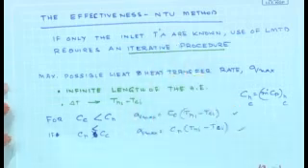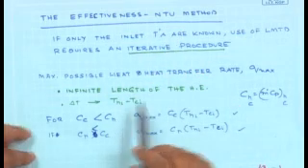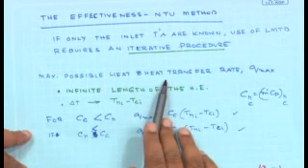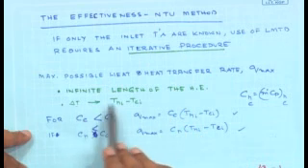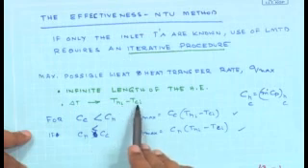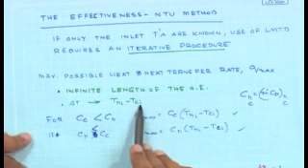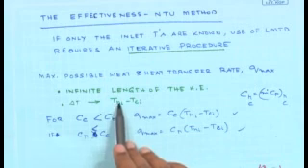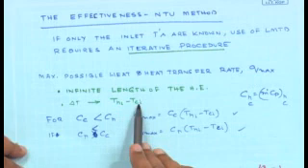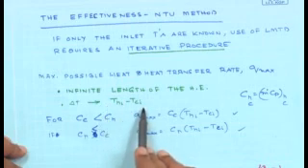So I'll quickly go through the slides which we have discussed in the last class, and then move on to derive the final relation. What we have done in the previous class is we started to work on the epsilon-NTU method. The maximum possible heat transfer can take place when the temperature drop goes from Thi, that is the temperature of the hot fluid, to Tci, the temperature of the cold fluid. That's the maximum possible temperature difference that exists in a heat exchanger, and if the temperature of the hot fluid reduces to the inlet temperature of the cold fluid, this is going to give rise to the maximum possible amount of heat transfer.